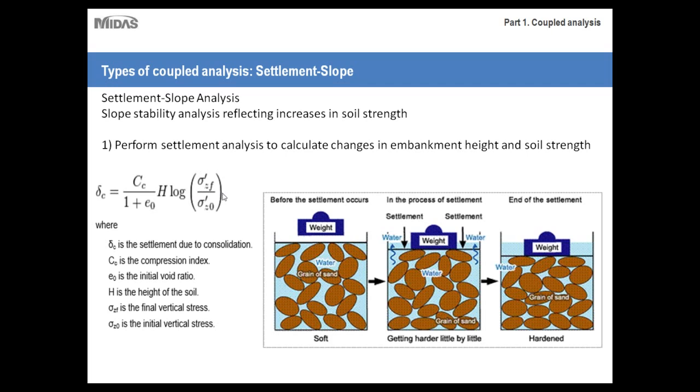It's also easier to visualize with numerical modeling. But the settlement itself is based on a logarithmic equation over time. I won't go into too much detail, but keep in mind that because of this level of complexity with consolidation, numerical modeling or a spreadsheet would be your best bet, whereas doing hand calculations would take an exorbitant amount of time.